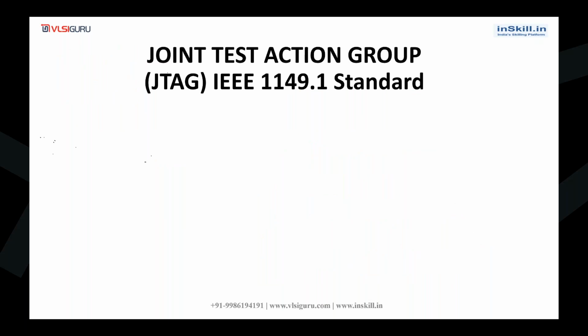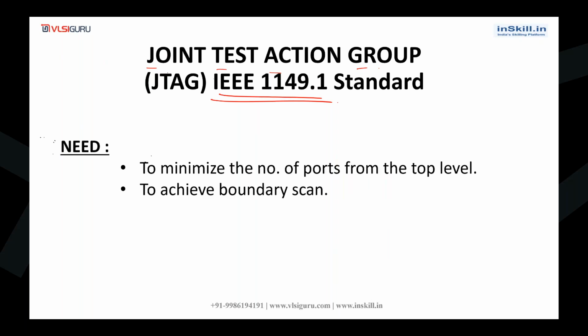The next topic is JTAG. The full form of JTAG is Joint Test Action Group. It's an IEEE 1149.1 standard. So why do we use JTAG? We use JTAG in order to minimize the number of ports from the top level and also to achieve boundary scan.